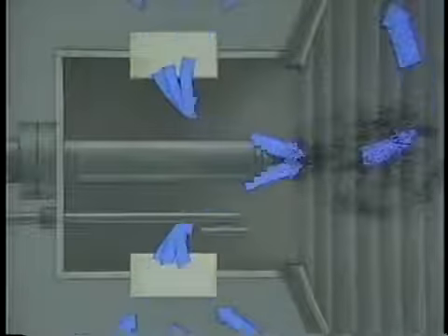If airflow is subsequently reestablished, this large concentration of fuel can ignite suddenly and cause an explosion. Interrupting fuel flow will also extinguish the boiler flame, and unless steps are taken to correct the problem according to procedures, an explosion may result when fuel flow is restored.